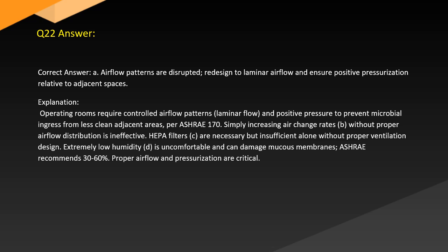Simply increasing air change rates, B, without proper airflow distribution is ineffective. HEPA filters, C, are necessary but not sufficient alone without proper ventilation design. Extremely low humidity, D, is uncomfortable and can damage mucous membranes. ASHRAE recommends 30–60%. Proper airflow and pressurization are critical.